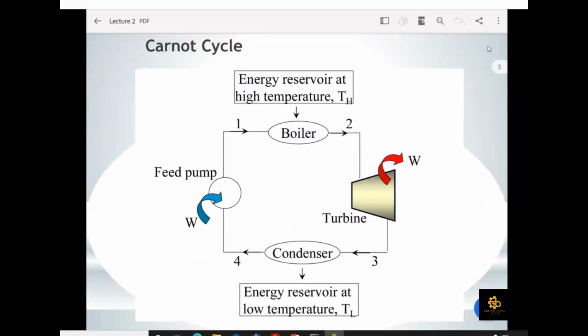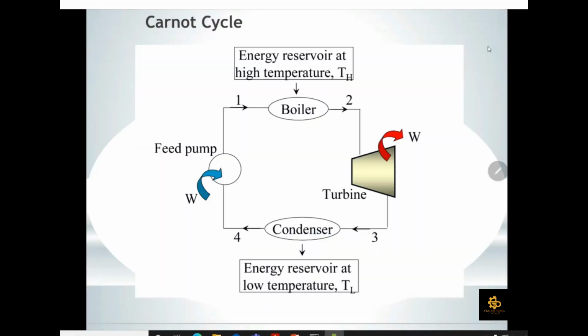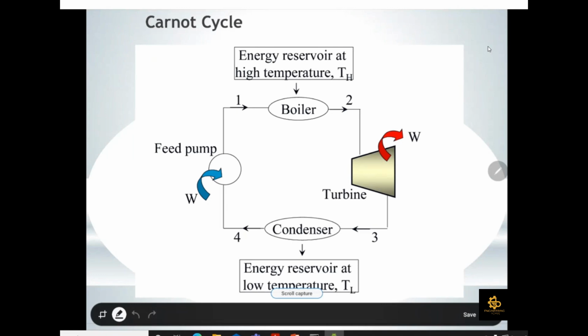First, you have knowledge about the Carnot engine or Carnot cycle. So what is the Carnot cycle? The Carnot cycle is one of our idealized cycles. You all know that it has a maximum efficiency. But here the question is, if the Carnot cycle has maximum efficiency, why are we going to study different types of cycles and why do we have to build different types of cycles? Why do we not run our steam power plants, our power producing devices, on the Carnot cycle and produce maximum efficiency? This is the best possible solution in order to gain a lot of work from our steam power plants. But there are some limitations of the Carnot cycle.